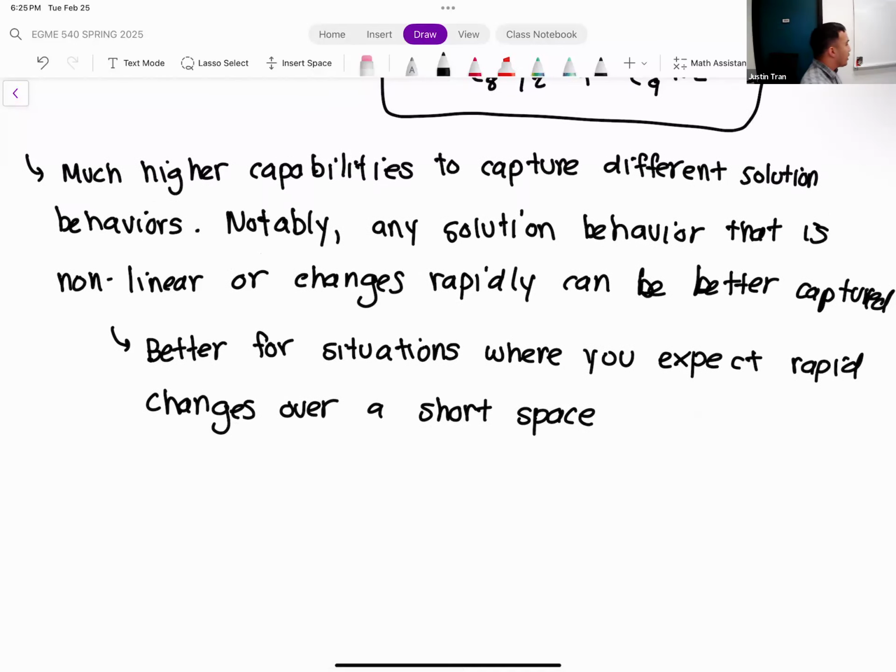But of course, just like we talked about at the beginning of the class today, sometimes these extra terms can also be useless. If you don't have rapid changes or complex dependency, you may just do all of this computation just for numbers. And in 3D, it makes a pretty big difference, because if you look at the number of terms in the shape function for the quadratic tet compared to the linear tet, there are 2.5 times more terms in the quadratic tetrahedron.